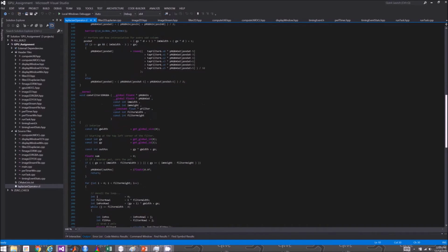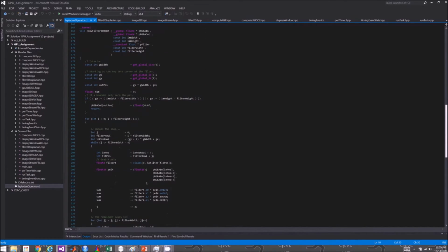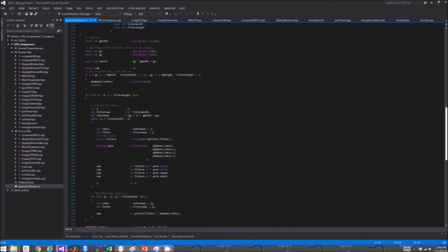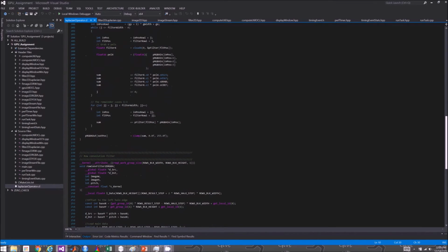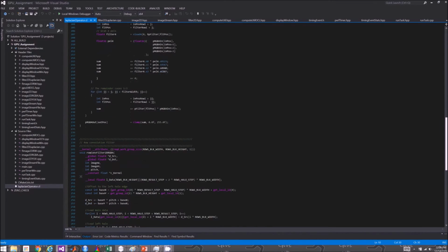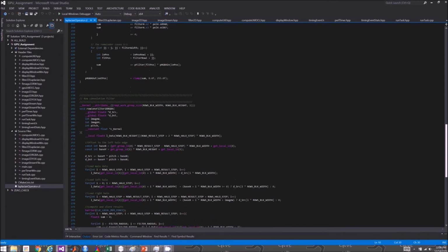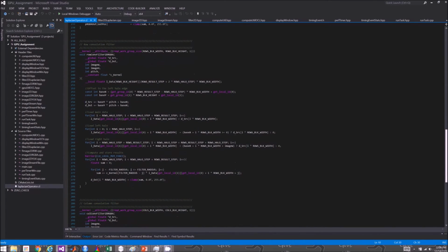And finally, we have our convolution filter. This is a partially unrolled convolution filter that enables us to operate on 4 pixels at a time for each iteration. Any remaining pixels, because of the filter width, are processed at the end of the loop. Lastly, we also experimented with some separable filters, but these are not applicable to the Laplacian case, but for completeness, they were performed anyway.